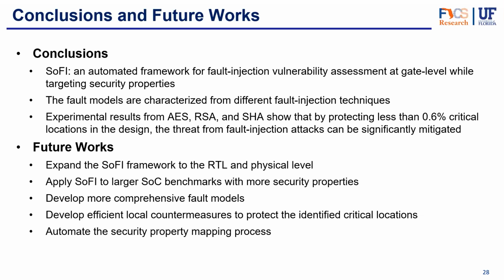So not only the countermeasures that we thought can be applied locally, but there are some other countermeasures that we can consider. For example, if I'm talking about a specific net in the design, and I know that it's susceptible to one type of attack, then maybe by changing the gate type, or different characteristics of that transistor, like changing the width of that transistor, maybe we could, in a very, very local manner, prevent those scenarios.